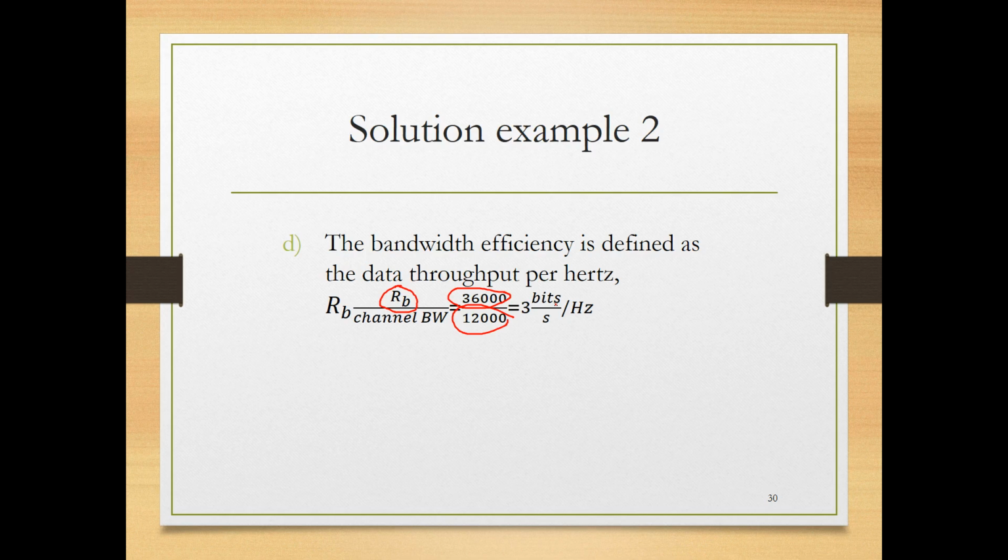This is a very comprehensive example, and the most tricky part of this example is the first thing, when we calculated the number of required quantization bits by understanding the relationship between quantization, noise, delta, and the condition 0.01 peak to peak. Then the second tricky part of this question is how to differentiate between the number of levels that represent quantization and the number of levels that represent modulation. You must not confuse yourself between them. That's different than that. This one for quantization, this one for modulation.